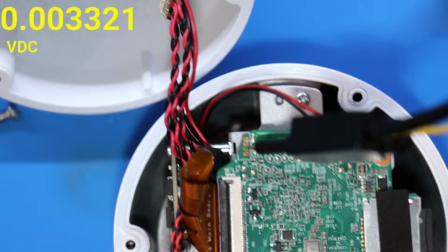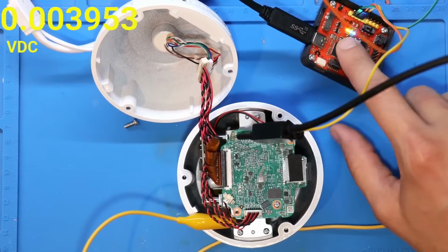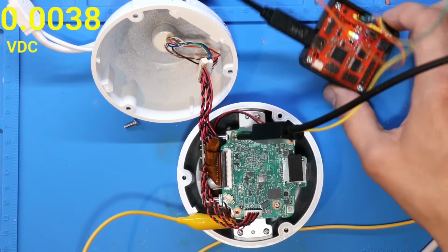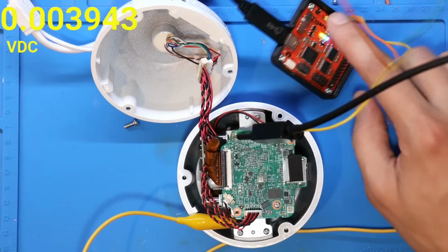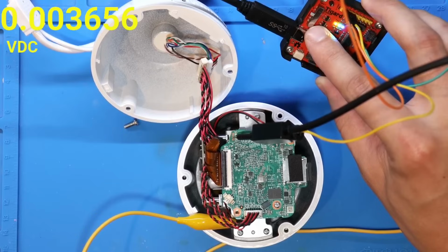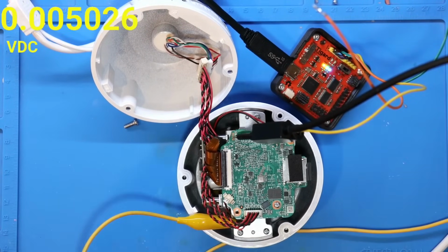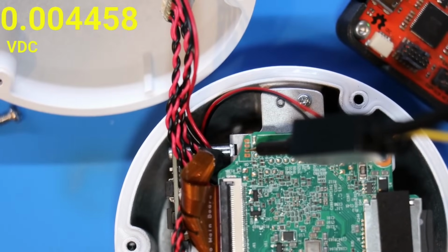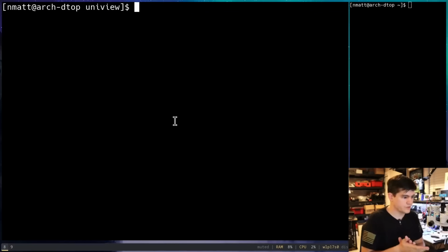All right. So just to zoom back, all I did is plug in USB. And the thing I really like about this TiGuard, instead of the dedicated, single voltage UART adapters, is it has a toggle switch right here. So I can make this be 5 volts, 3.3, 1.8, or take a reference voltage. So this one device will do all those different UARTs, which is nice to have. All right, so I think I'm still connected up to there. Let's come back over here to our computer.